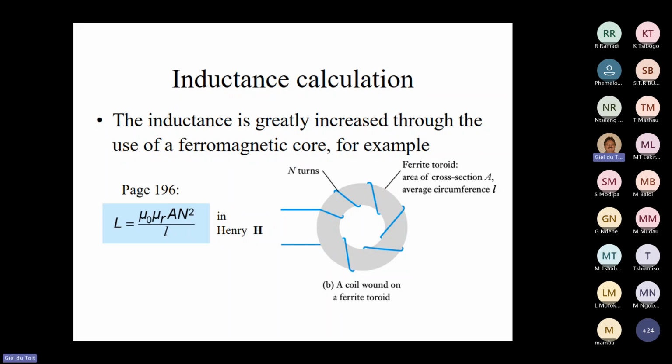This cross-sectional area you cannot do in square millimeters. You must convert it to square meters. And remember, there is 10 to the 6 square millimeters in a square meter. Okay. 1 square millimeter, how many square meters is it again? I always ask that in class to sharpen you up. And even today, a lot of people don't know. It is 10 to the minus 6 square meters in a square millimeter. So learn to convert, learn those conversion formulas on page 16 and 17 in the handbook.